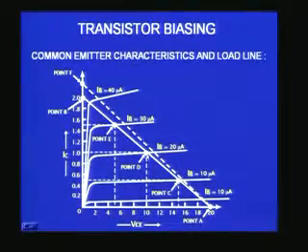So let us say the point D. The moment I operate the transistor at the Q point corresponding to point D on the graph, my collector current should be around 1 milliampere, as you can see on the x axis corresponding to this point D, and I must have the voltage between the collector emitter to be around 10 volts with a power supply which will be operating at 20 volts. The VCC supply is 20 volts and the 10 volts will be the voltage across the collector and the emitter, and 1 milliampere current will be the current through the collector. So how do we arrange so that my transistor is at this point, is what we now call as the biasing. So we discussed two different types of biasing.